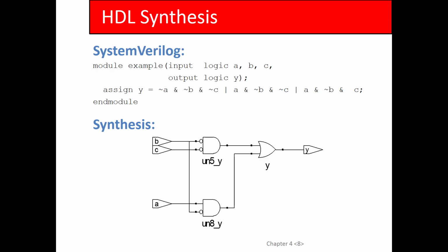Yes? And is that the lowest amount of gates and everything that you could get? Not necessarily. That's the other thing: is this minimal? I don't even know. Well, clearly they minimized it, right? Because the way it looks, there's 1, 2, 3 input AND gates, and 1 3 input OR gate here. Sum of products, right? This sub-expression can be done with 1 3 input AND gate. This is 1 3 input AND gate. This is 1 3 input AND gate. And this whole thing is 1 3 input OR gate. But yet, not what we got.